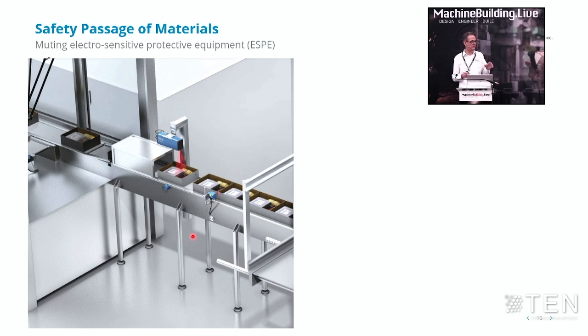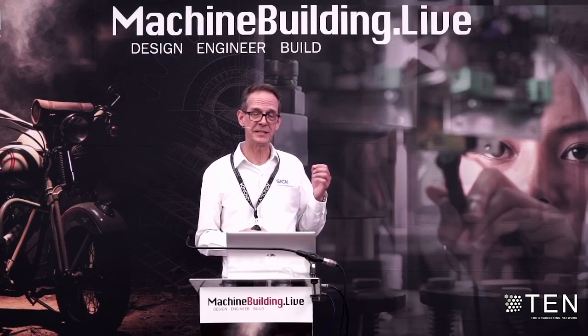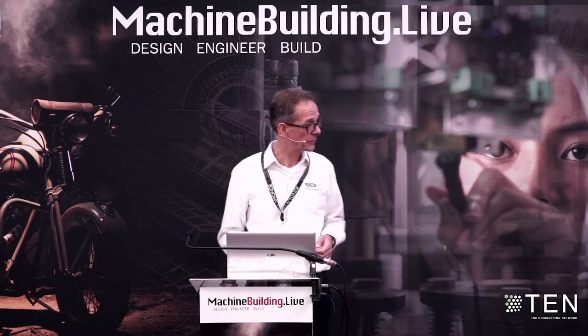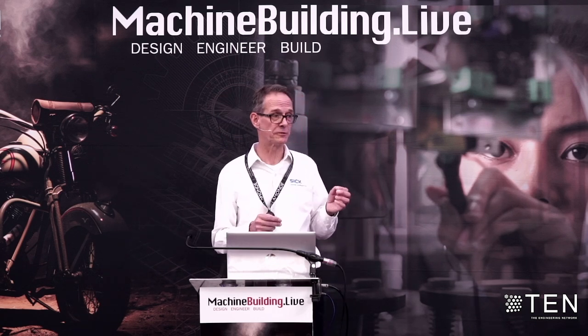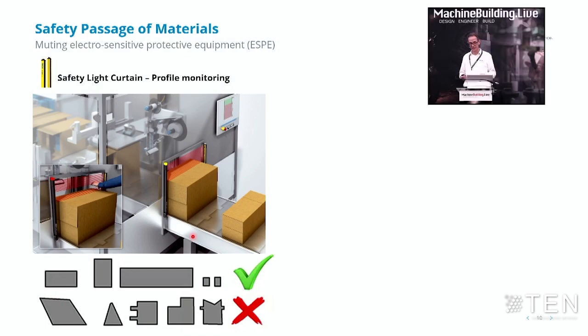What we've found very recently in the last couple of years is there are more and more applications with smart packaging machines, with courier express parcels, where they want operators in close proximity to the machine, and these tunnels are not an ideal solution to have in that environment. With this, we've come up with another light curtain solution, which is light pattern recognition, but it's looking at profiles. The light curtain can be mounted in the vertical orientation.